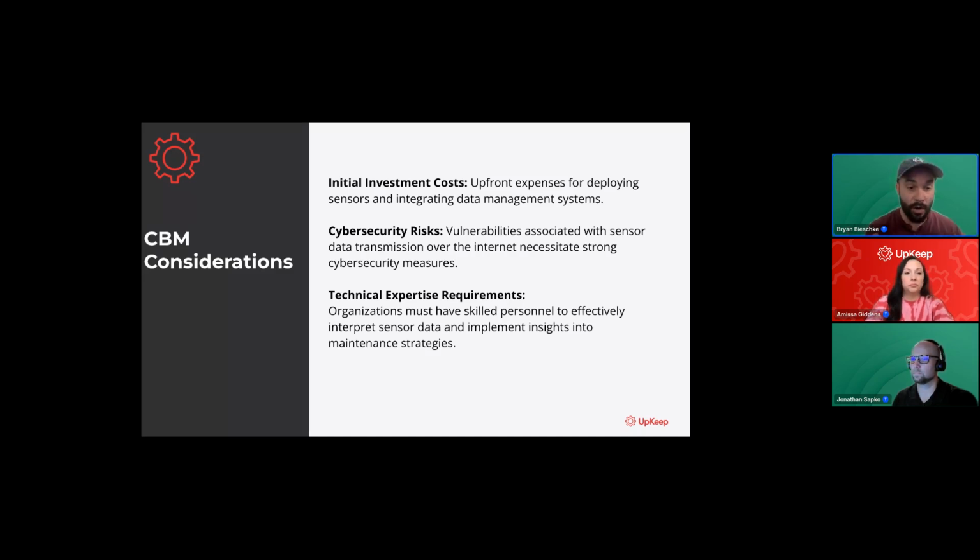And then this is the biggest one, technical expertise. If you don't know anything about vibration sensors and you want to put vibration sensors all over your stuff, you better call somebody like Matt Knuth, because you need to have expertise in these environments. As great as it is, you can't just plug and play. You wouldn't believe we find sensors installed wrong. We find things hooked up incorrectly. We have the wrong RPM data. There's just so much that happens when we're confiding in that sensor to tell us something and it's set up wrong. You need to consult experts in this field.